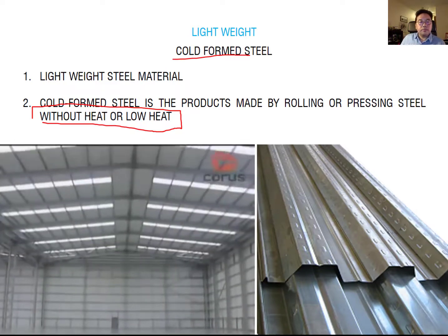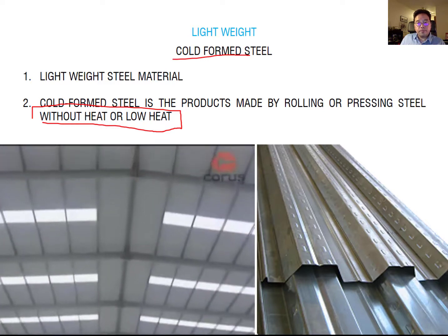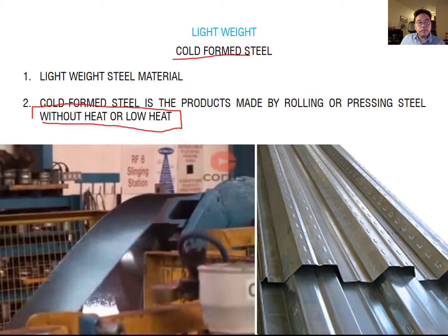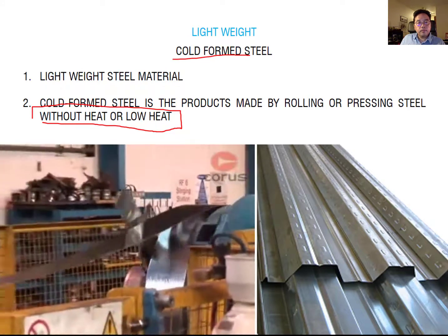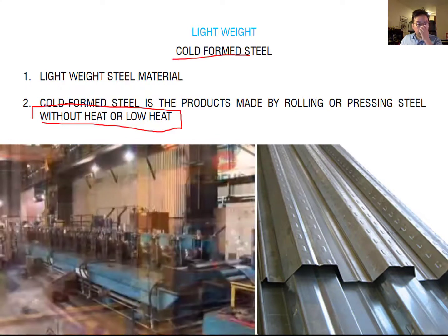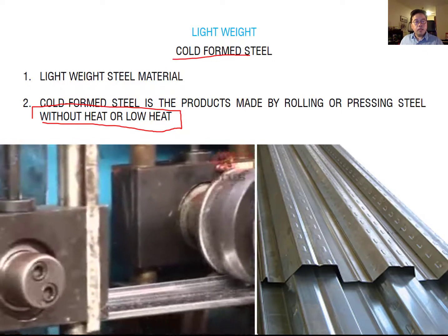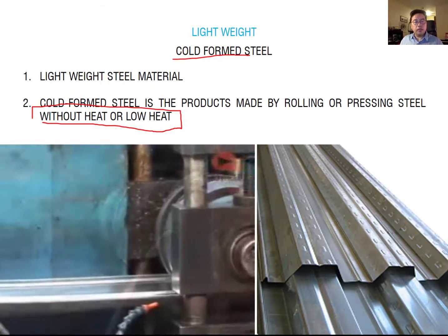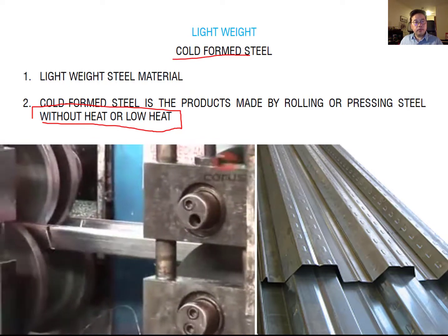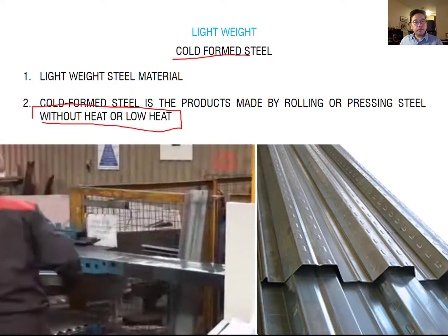Cold formed sections are used for a number of different applications, primarily associated with either the building envelope or light steel structural elements used in walls, partitions or floors. For building envelope, narrow strip steel is rolled into the sections required for purlins or sheeting rails that support cladding and sheeting. It is also pressed to form gutter profiles and flashings. It's also a very popular material for the metal stud, for your wall, for your ceiling. For light steel framing sections, the narrow strip is rolled into C-sections that are built up into walls or whole modules before delivery to site.